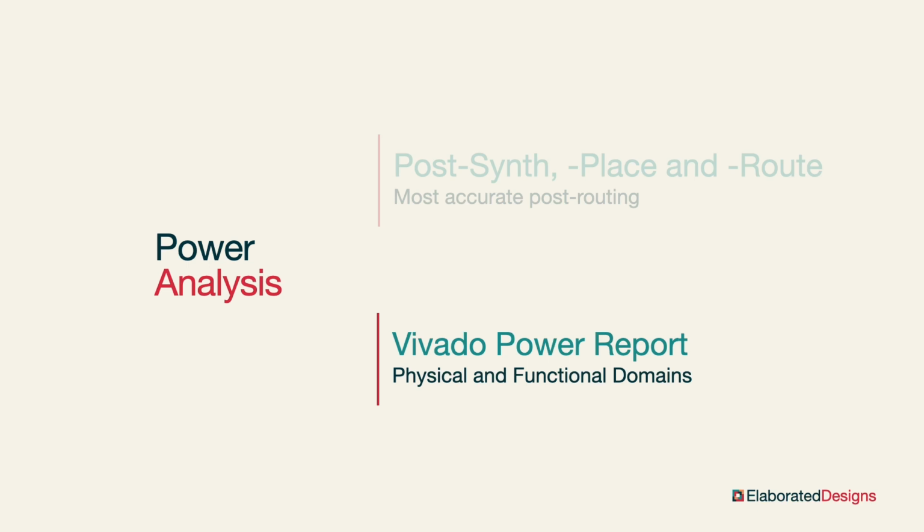Information from the functional domain includes the type of logic in our design, like the number of registers, block RAMs, and transceivers, as well as the switching activity, like how often the signals in our design change state and how long they stay asserted. As FPGA designers, we are responsible for generating the information in the functional domain.